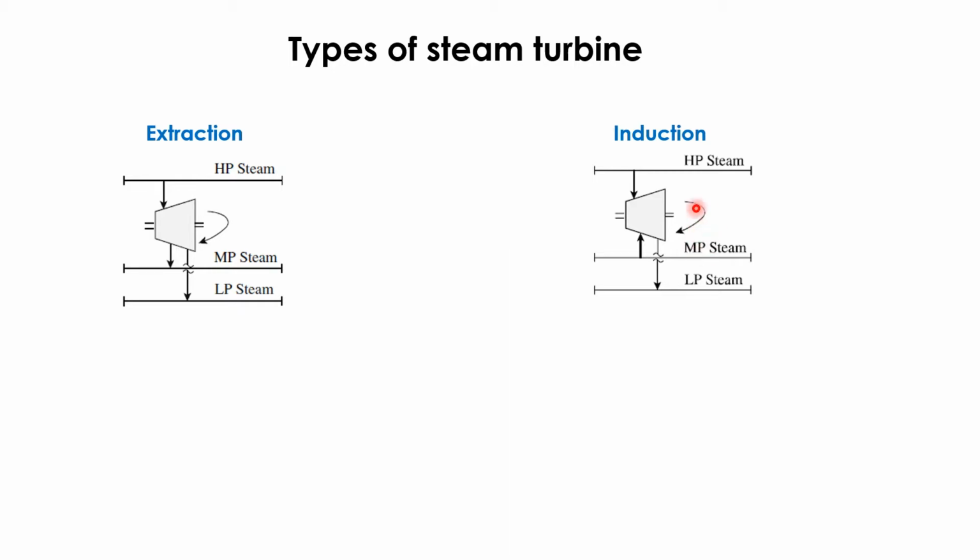In the situation shown in this image, an excess of medium pressure steam generation over and above that for the process heating is used to produce power and exhaust into the low pressure steam here, where there is a demand for the low pressure system for the process heating.